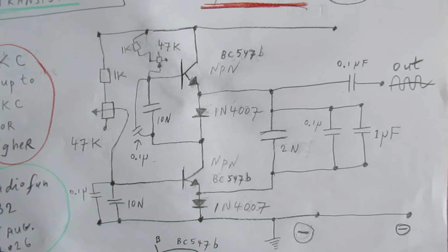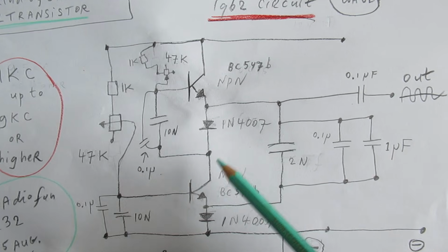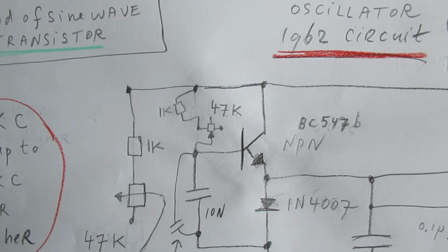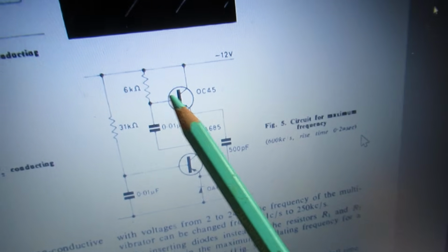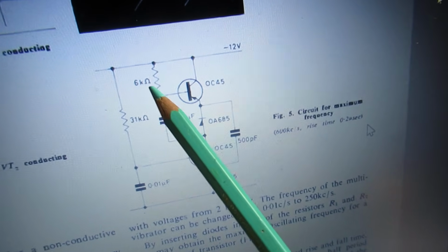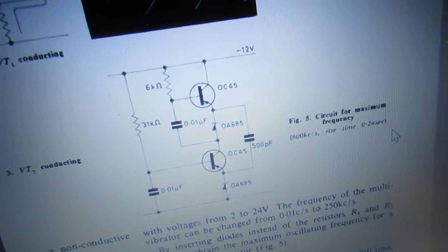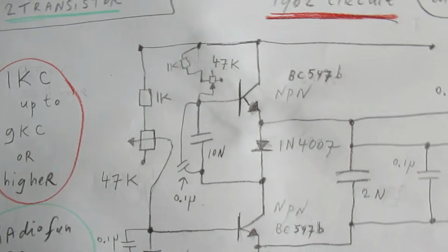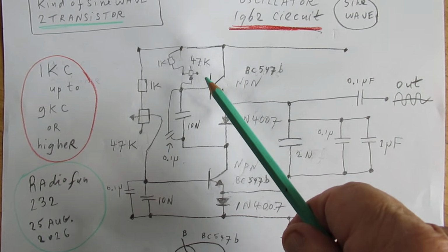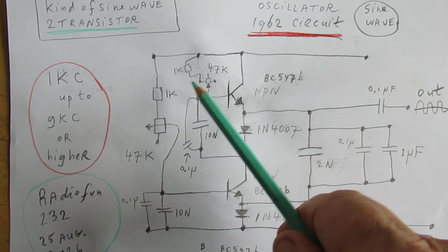And also here, of course, when you do all these experiments, you must be able to set the bias to each transistor differently, and that's done here by not using, say, the fixed value resistors that are told here. In that case you will never get it working with another transistor or other type of transistor, or a silicium transistor or other type of germanium transistor. So use here a potentiometer to align the bias of this transistor and align the bias of this transistor.